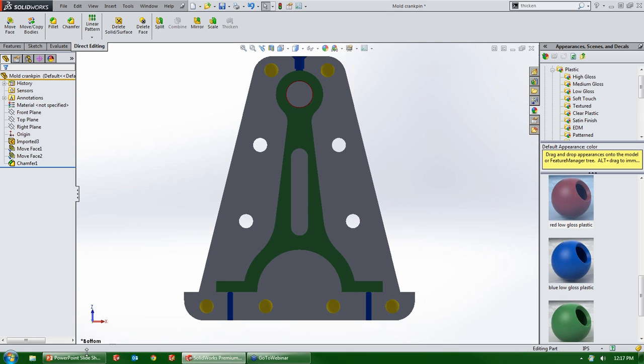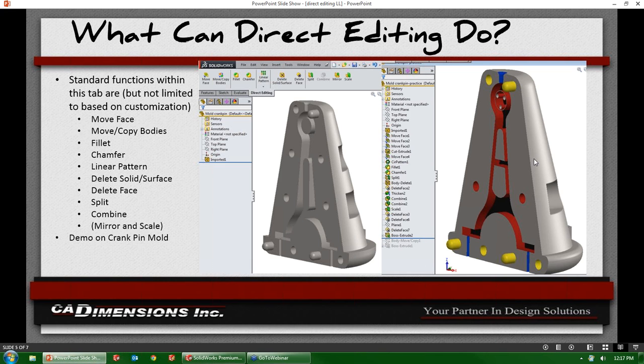All right. So I'm just going to jump back into the PowerPoint to see what our next step is here. So we've updated our insertion point. We've added draft to here, and we've corrected our depth. The next thing I'm going to attack is the center slot. So the original geometry that I got off of GrabCAD is just a simplified slot. What I want to do is add some support to this and stay parallel with the outside of my crank pin.